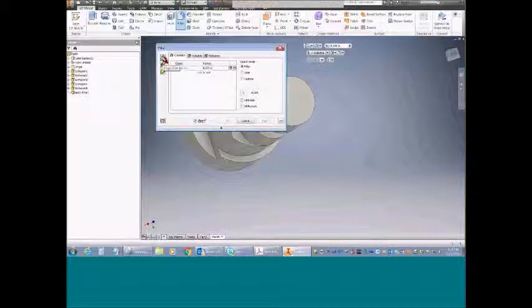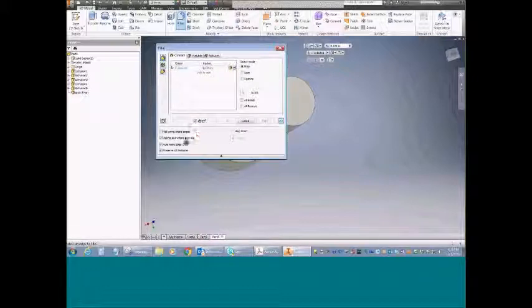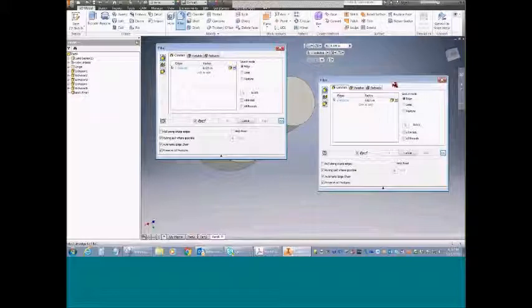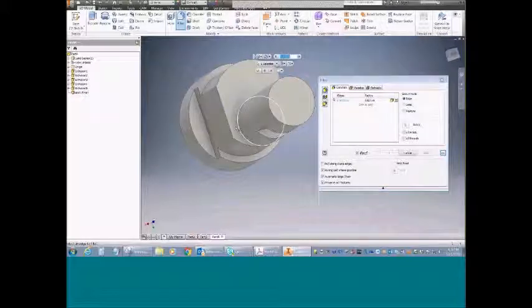We can edge fillet, we can fillet faces, which we don't have any right now. Then we can do a full round fillet. There are some different possibilities down here, so we can roll along sharp edges, roll the ball when possible to keep our fillets nice and fluid, and so on and so forth. So on this one, our fillets are 1/8 of an inch, perfect. So I can just go through and select the edges I want to fillet, which should be these.